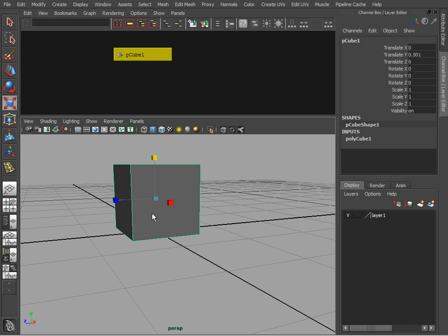This is how we can change the pivot point location, and in order for us to do that, we need to switch to the edit pivot point mode. The way to do that is to use a hotkey. One hotkey that's more or less universal across different operating systems and keyboards is holding down D, as in dog. While you're pressing that key down, you can move and adjust the position of your pivot point.